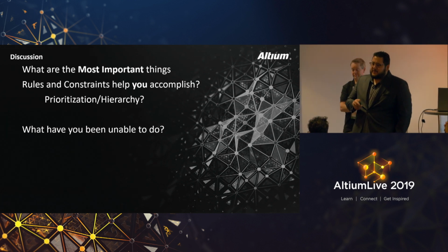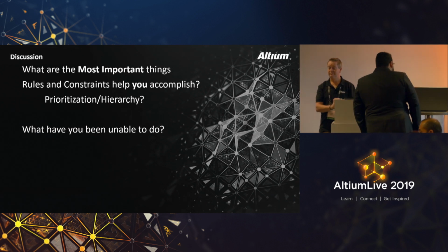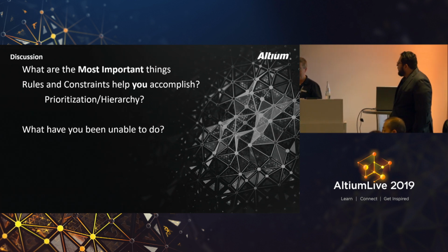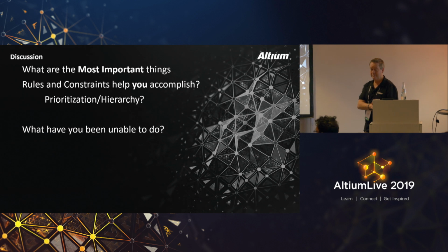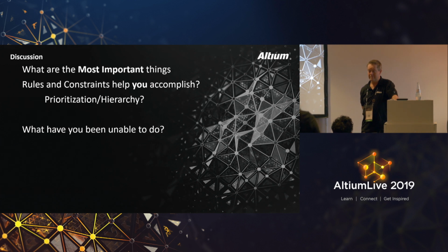I think one cool feature that was introduced in 19.1, I think, is that you can define directly in the footprint that a pad should be connected without a thermal relief. So this is for us very useful to simplify the DRC rules. For example, for a MOSFET, we define the exposed pad, the thermal pad, that it should be directly connected and not over thermal relief.